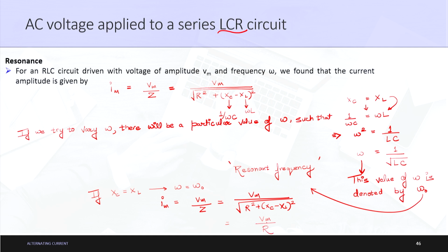If you look at this very clearly, the value of Z obtained when Xc is equal to XL is the minimum value we can obtain for impedance. If Z minimum is obtained, then it is very clear that the amount of current produced is maximum. So, if Z is equal to Z minimum, that simply means Im is Im max, correct, and that is the concept of resonance which we require. What is the basic concept of resonance?